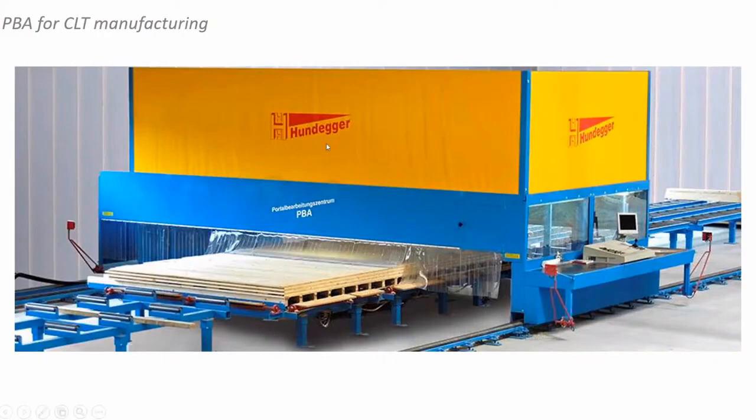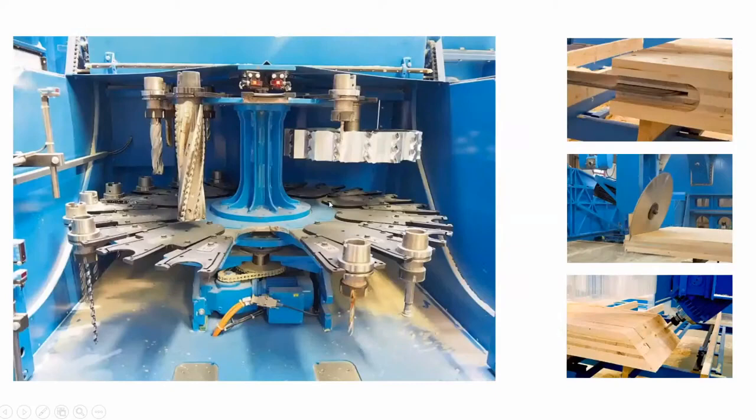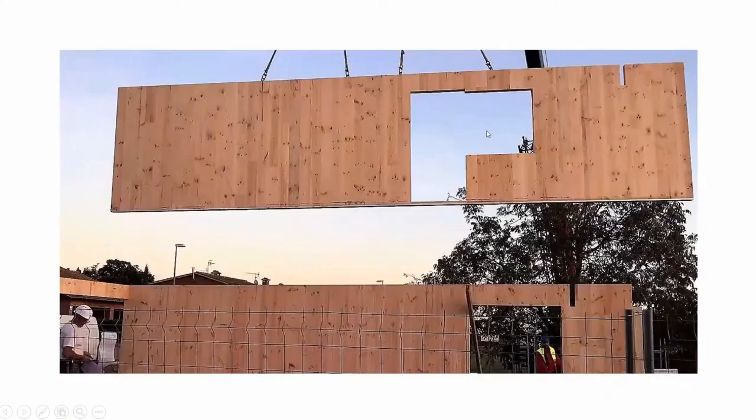For example, the company Hundegger is one of the leaders in the market in terms of joinery and CNC machining of timber, and also CLT elements. They have a lot of machining tools, which you can see here, that allow many variations of subtractive processes, and that way machine a standard rectangular CLT into a more individual piece that can then be taken on site and assembled.